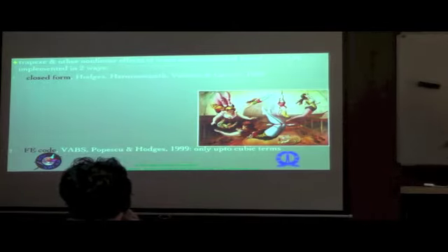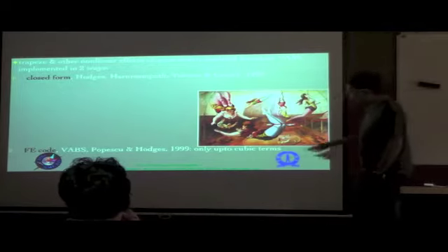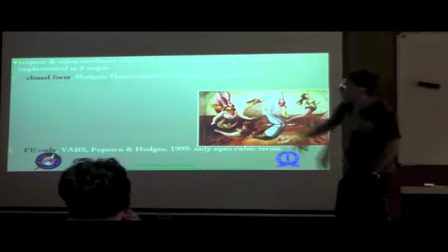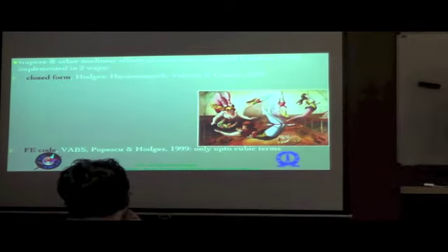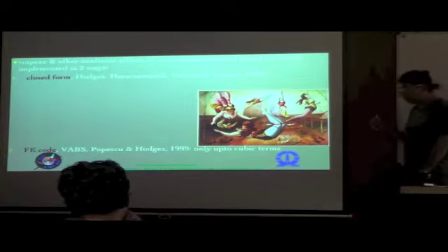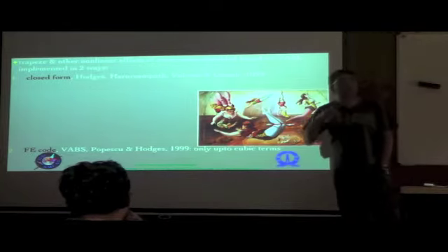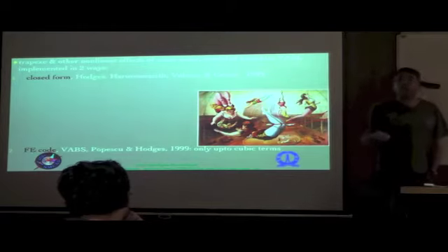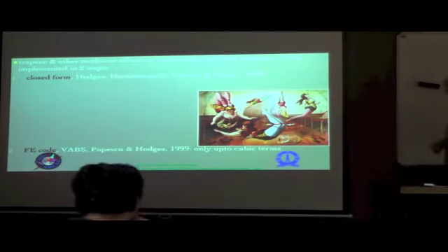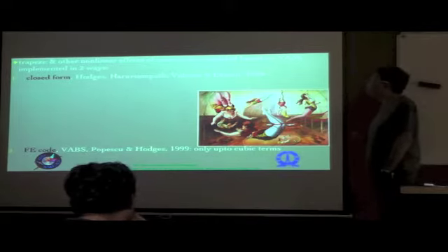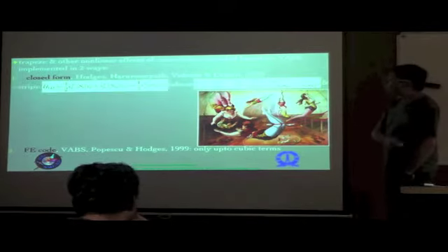But in all such situations you will see that only up to cubic terms are included in the software, whereas in the closed form analytical solutions you have all the way up to quartic terms, for not only thin rectangular cross sections but also for thin-walled open cross sections like I sections, channel sections, hat sections, the cruciforms that I talked about, etc. So how does it look?